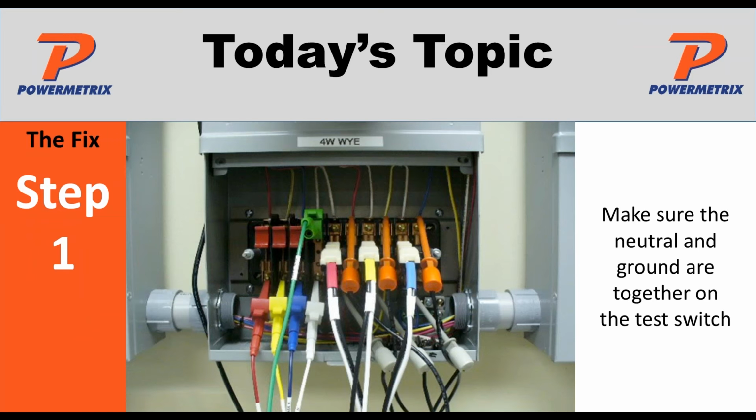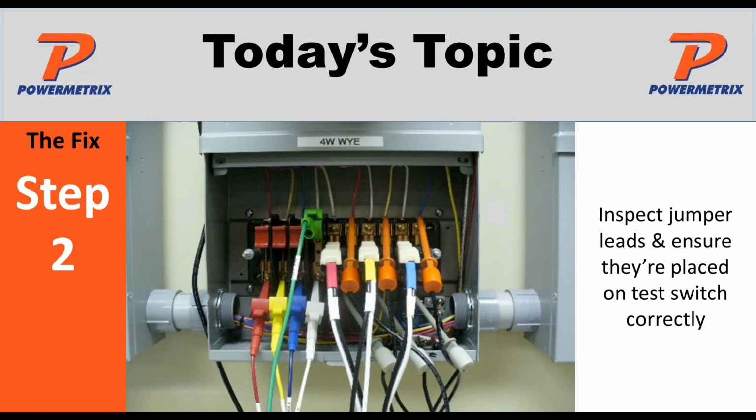Fix number one, if everyone can see that picture, this is the proper way to hook a PowerMaster 7 series or 5 series with a current source capabilities. Make sure the neutral and ground are together on the test switch. And you can see the neutral doesn't have a handle itself, but it's a flat bar there that the neutral and the ground are hooked together. And of course you've got your jumpers, your current jumpers. Okay, so let's move on to step 2.